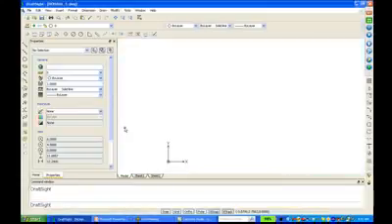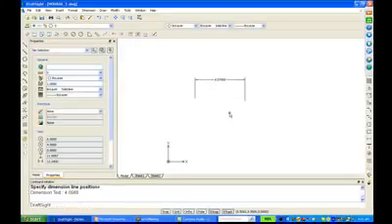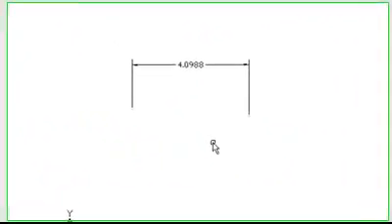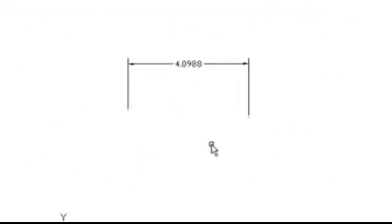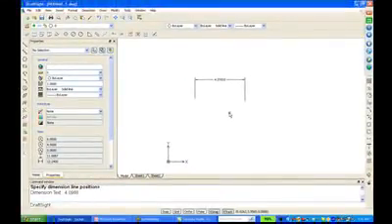So the first thing we need to do is get into DraftSight. When you open DraftSight, you automatically get a default drawing, and that's your standard template. If you look into your standard template, I'm going to throw a dimension on here. And as I dimension this, you'll see that the dimension comes out with 4 places after the decimal point. Most files in the US, we don't need 4 places after the decimal, so we probably want to update and change that. We'll do that in a bit.